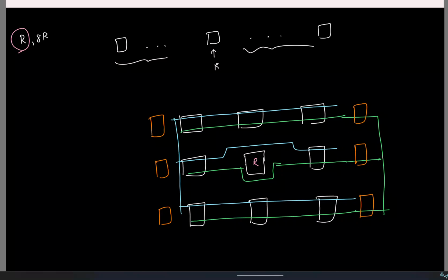Okay, but yeah, the problem in doing common centroid is that you see the routing becomes slightly complicated, right? That is the price you have to pay. So basically there are 3 things you always do. First, you replicate stuff. If you want a dimension which is larger or smaller, you put smaller devices and put them in series or parallel. So always replicate and connect in series or parallel to get larger or smaller dimensions.